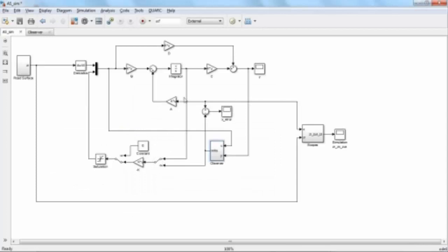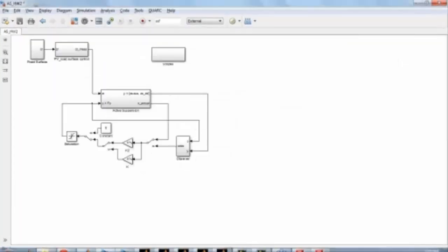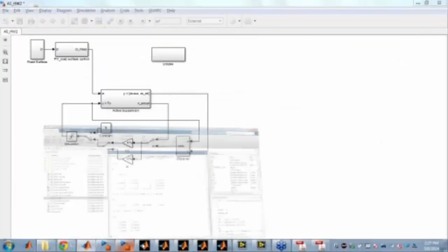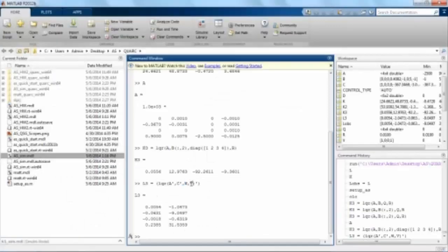And then go back from actually tapping directly into our system states, but rather using the observed states instead as feedback for our LQR design. And this whole setup, if I have an observer design combined with an LQR design, that's what we call an LQG design. Now the weighing matrices, I should probably point out at this point that we used here, my W and my V.